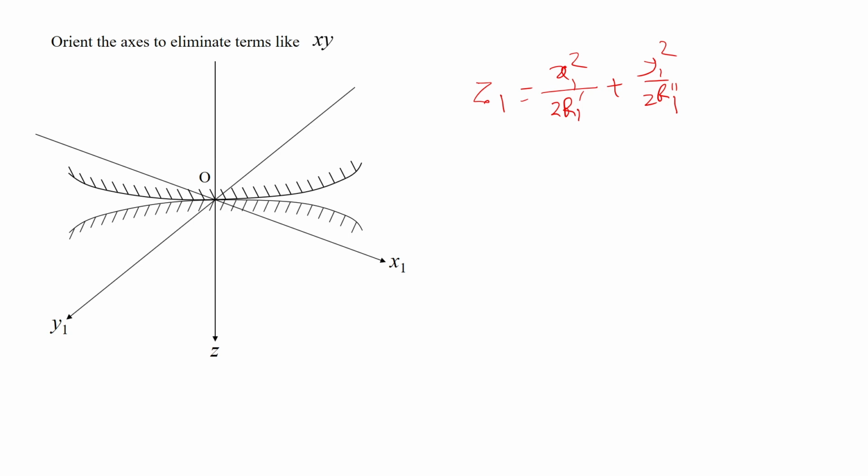Any surface, at a point on a surface, we can think of several different radii of curvature at different planes, right. But then there are actually two planes which are perpendicular to each other, at which the radius of curvature is maximum or minimum. These are called the principal radii of curvature. So, here these are the principal radii of curvature.